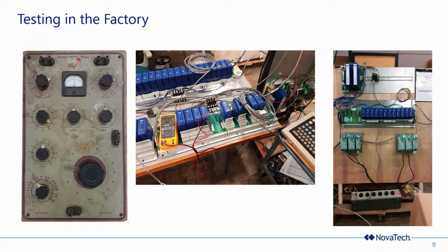We've also done other types of testing. This is testing for the cabinet that's in Mexico that I showed you earlier. So this top rack, in this case, holds the E-beam, some switches, the I/O carrier that replaced the Quantum I/O, and these are 12 and 24 volt power supplies mounted on aluminum panels, and the holes in the panel exactly match the holes that were there for the existing power supplies that they were replacing. So again, all good engineering design up front to minimize time and installation and ensure success.